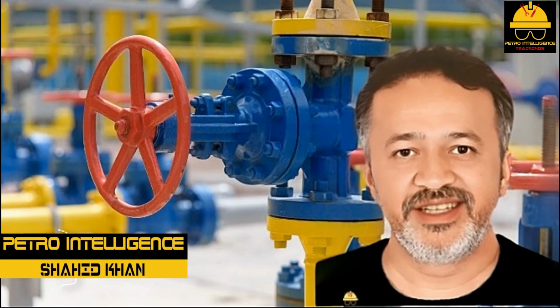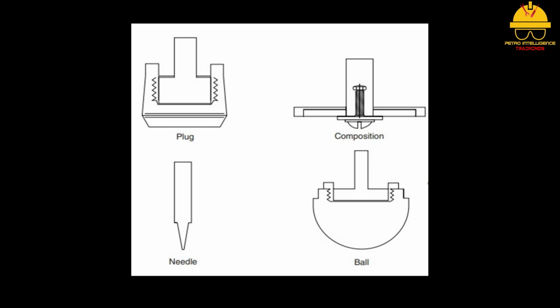For common disc designs, the disc on a globe valve comes in a variety of shapes and sizes. The four most common designs are plug, ball, composition, and needle as shown in picture. The plug-type disc is used for throttling. It is equipped with renewable seat rings on a cone-shaped mating surface. It is the best device for throttling and in situations with wide temperature and pressure variations. The ball element seats against a beveled, ball-shaped, or flat surface. It is designed for on-off applications that have minimal throttling.